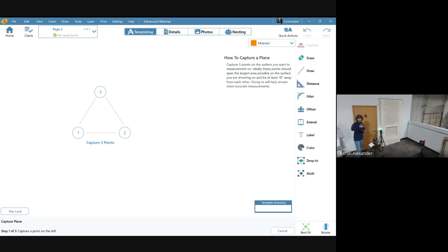So even though, which you guys may have found when you get out there in the field and you're trying to set a plane on something this tall that's only 5 inches wide, typically you could shoot lower left by the wall, right out in the front, kind of in the middle, and then top back towards the wall. The laser's going to tell you did a bad job because those points have less spread than we're looking for, right? So in the plane, we're looking for at least 12 inches of separation. And then we're looking for a certain degree of triangle, of depth of that triangle for the laser to say you did a good job setting the plane, right?